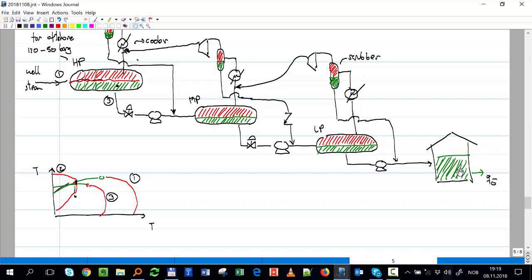Okay. If you make any other shape, say cylindrical walls, the walls of the cylinder and the two lids have to be of a higher thickness, just because of stress. A sphere is a configuration where the stress distribution is the smallest possible, and then the thickness can also be the smallest possible. So that's why you sometimes use spheres for LNG or LPG: they are pressurized, they have some pressure, so you have to make them such that they don't use too much material.